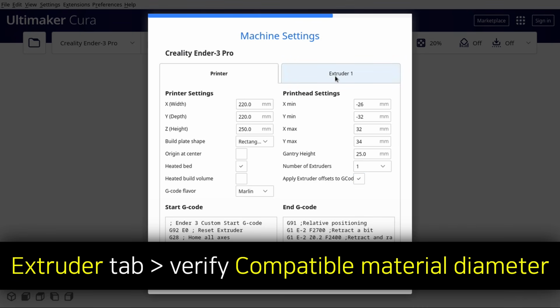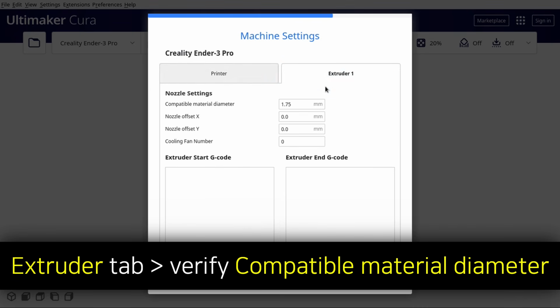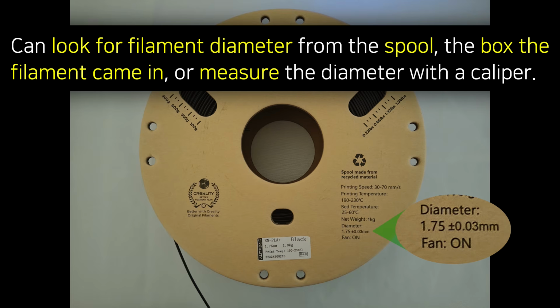Finally, we can go to the Extruder tab, where we can verify that the compatible material diameter matches the diameter of the filament we are using in millimeters. To figure out the diameter of our filament, we can look to see if the diameter is written on the spool of the filament. We can also see if it's written on the box the filament came in, or we can measure the diameter of the filament with a caliper.